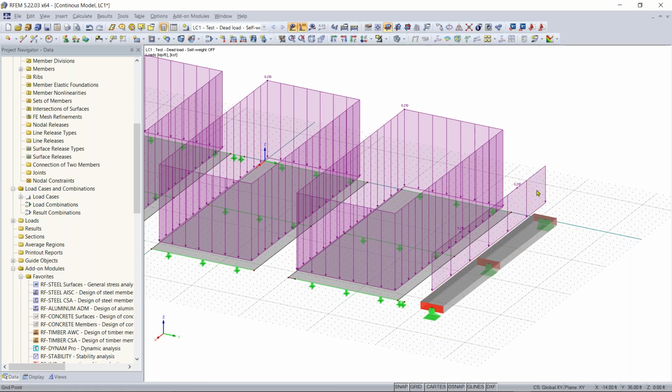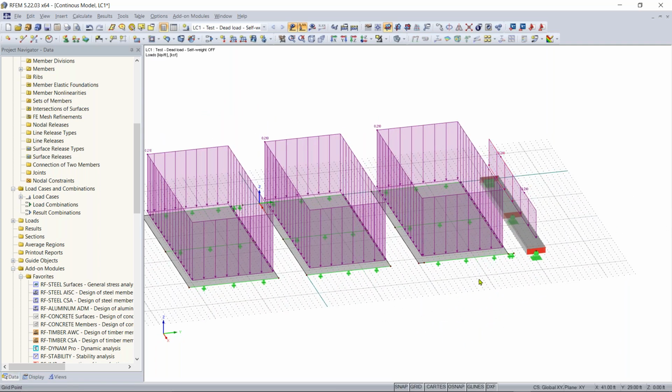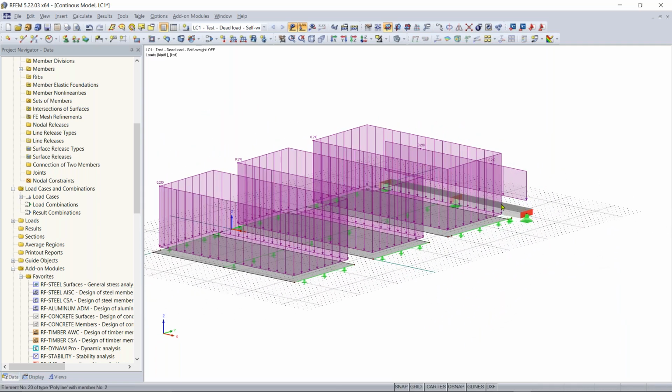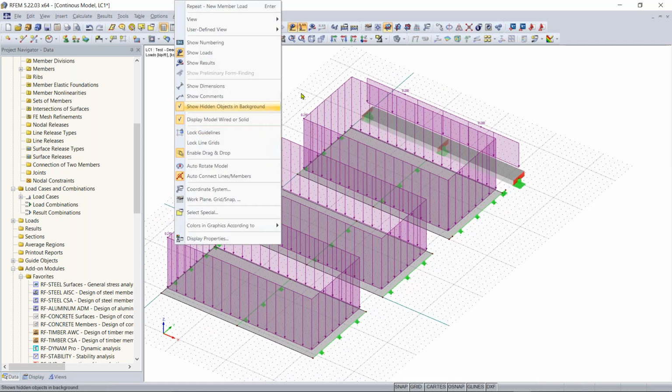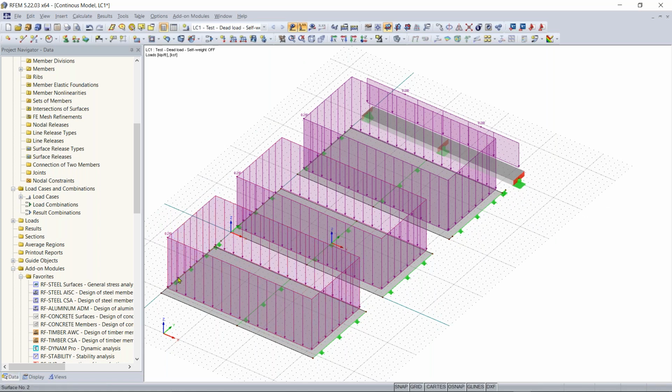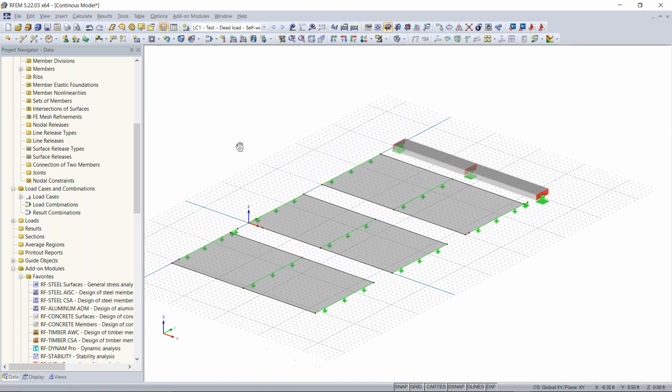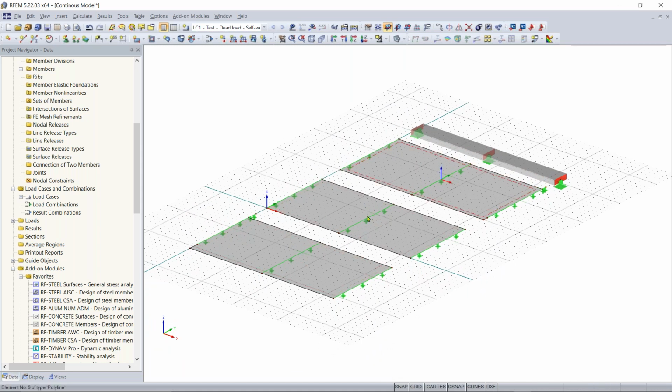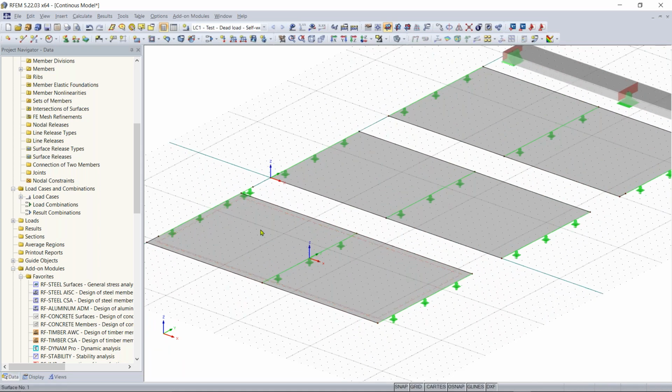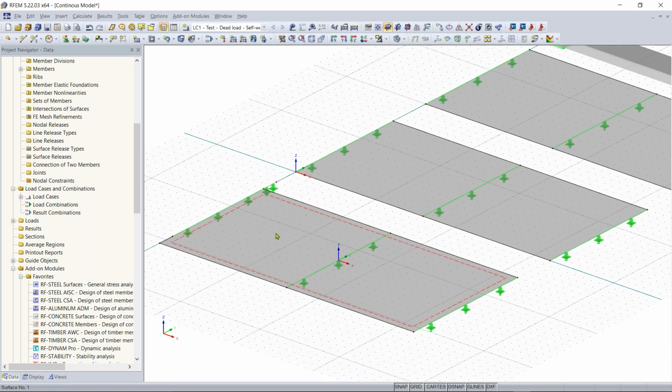I'm going to right click anywhere to get rid of that tool. And now the load of our structure or of our individual elements here, all of the loadings applied that we need to for this example. Another thing to keep in mind for your structure is the FE mesh or maybe the FE mesh settings. So normally you don't have to fool with this before you look at your results. But for this example, I would like to show you what having different sized FE mesh looks like. So this first plate here, we're going to have a larger FE mesh.